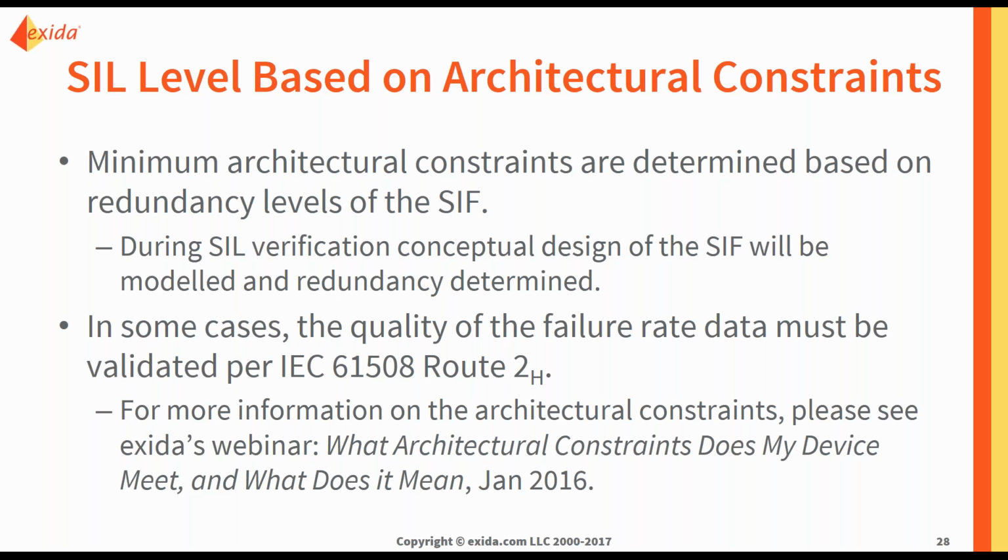So during SIL verification, you will put together a conceptual design by modeling the safety instrumented function, and this will determine your redundancy. In some cases, the quality of the failure rate data must be validated per IEC 61508 Route 2H.